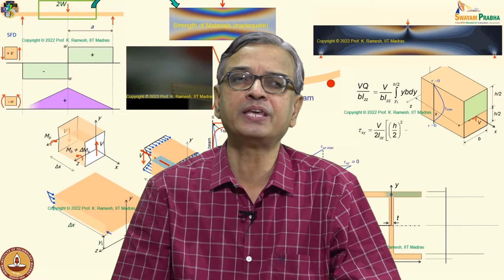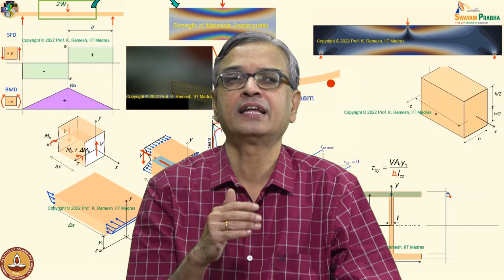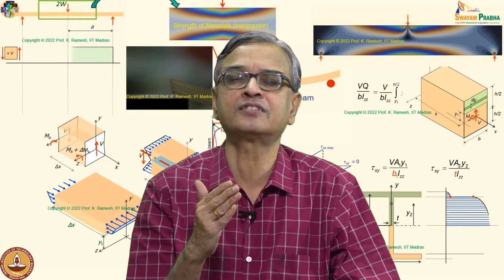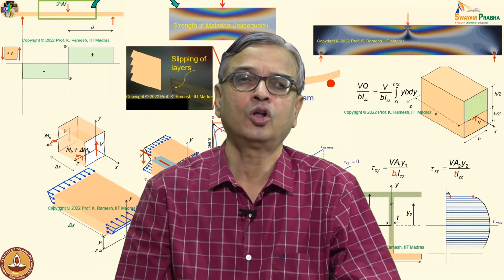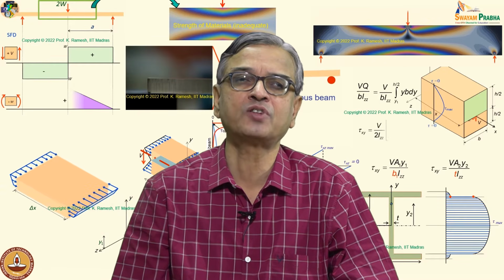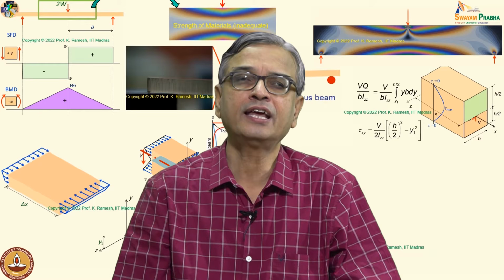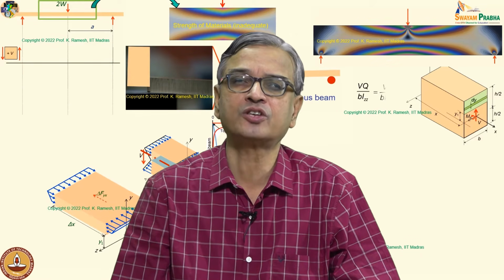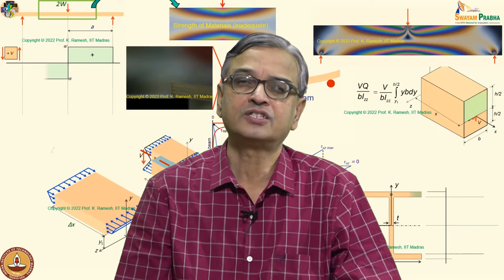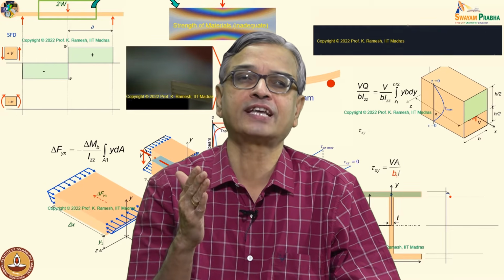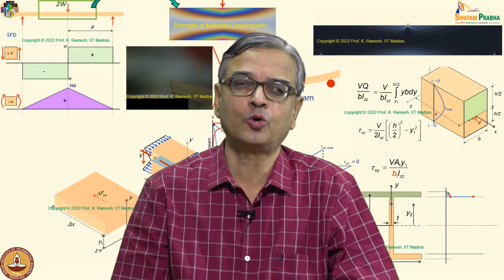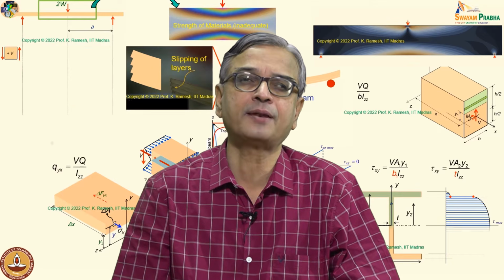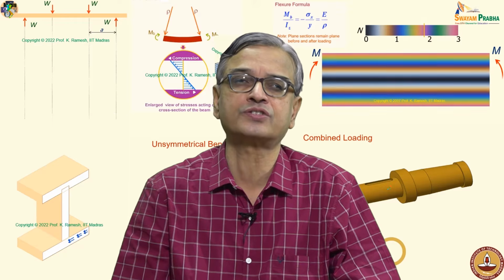Development of shear in beams is very subtle to understand, and this is systematically developed in this course by performing experiments on layered beams. Although shear stress variation over the depth of the beam is parabolic, near load application points this can be quite different, and the strength of materials solution is inadequate. This is well captured by a photoelastic experiment. Shear stress in open sections such as I-beams, concepts of shear center and unsymmetrical bending are discussed in this course.